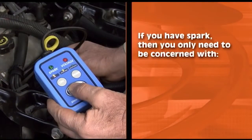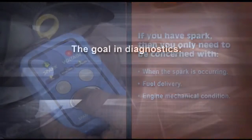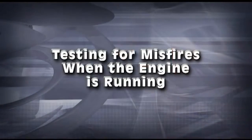If you have spark, then you only need to be concerned with when the spark is occurring, fuel delivery, and the engine's mechanical condition. The goal in diagnostics is to first confirm what's working, then you only need to test what isn't. We can cover more fuel-related and engine mechanical diagnostics in a future series of videos. For now, let's go back and talk about testing for misfires when the engine is running.